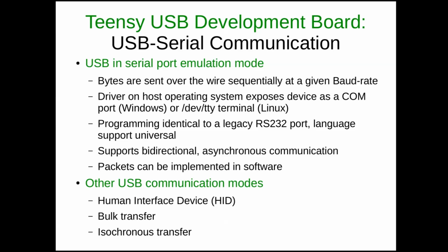This type of communication also supports bidirectional communication and asynchronous communication. This means that we can both read and write from a device, or we can send and receive data to or from the device. And we also can do this in an asynchronous fashion, where we don't really have to have a clock pulse or any sort of synchronization pulse to make this happen. So in other words, when the remote device, such as a microcontroller, wants to send something to the PC, it just sends it, and it doesn't have to signal to the PC that it's actually ready to transmit data. There are methods of serial port communication that have these sort of ready to send and clear to receive signals, but we're just using simple USB serial port emulation, which doesn't require that. So it's also very convenient to program.